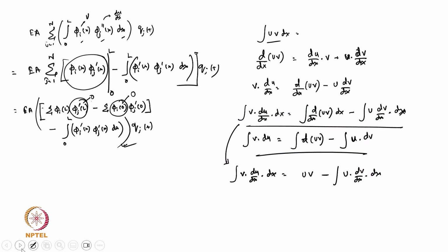In the second case your stiffness matrix was integral phi i into phi j double dash, but here the stiffness matrix of the finite element is this. So that is different. And in spectral element you cannot distinguish the two matrices, your stiffness matrix and mass matrix are fused. All more or less give the same result, but you can see they are in very different forms.